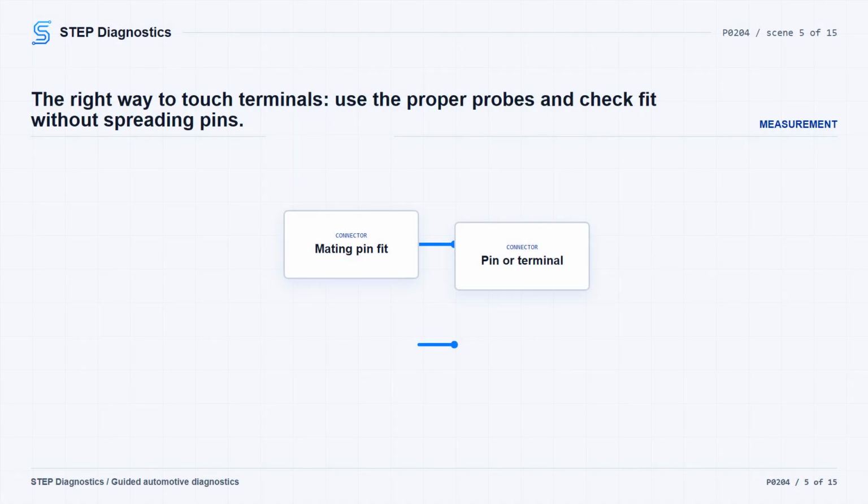When you connect test equipment or jumper wires at pins, use Rotunda Flex Probes NUD 105R025F or Terminal Probe Kit 418S035. The point is to test the circuit without spreading or damaging terminals.